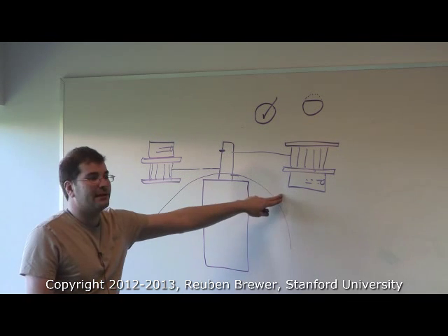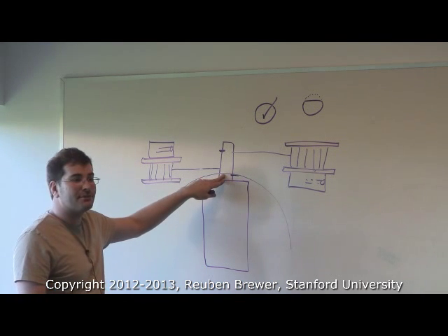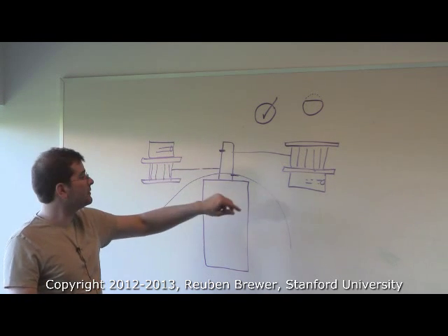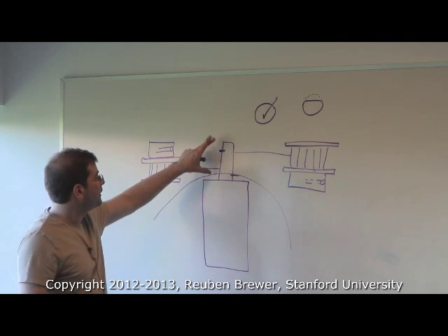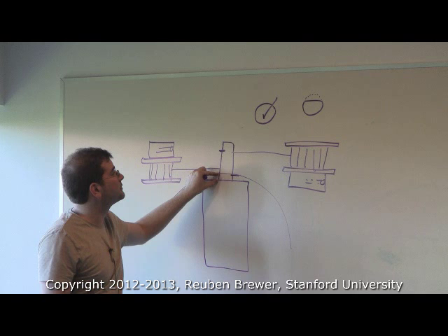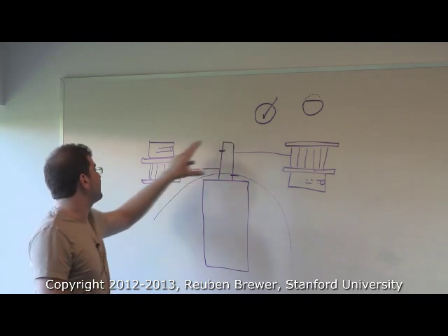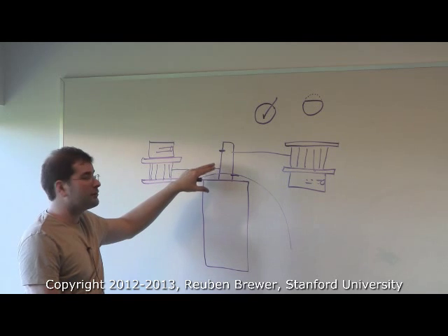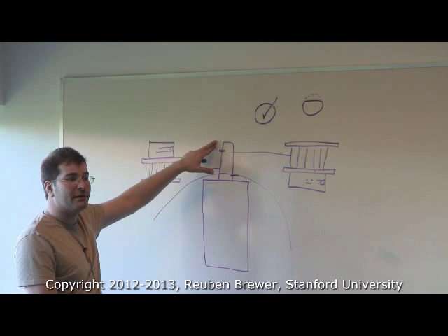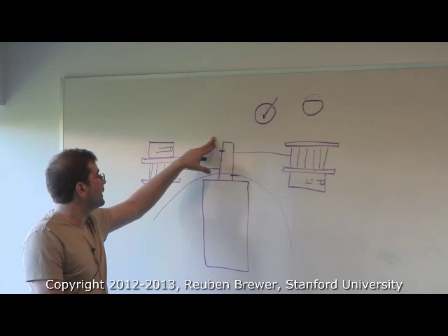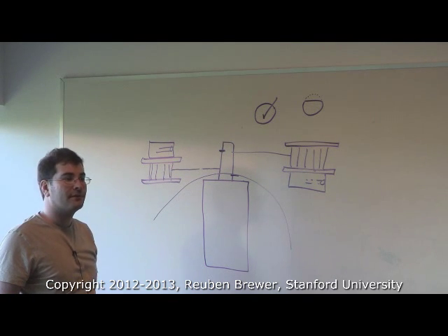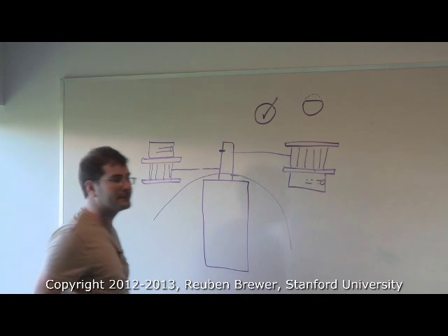Configuration upside down or right side up. If I do it this way, I have to dremel right next to the bearings, which is dangerous, and my force is higher. And if I dremeled the entire thing, most of the shaft is bad for locating. I only have this itty bitty little section of the shaft that's a full circle for locating. If I turn it upside down, my lever arm is smaller, so I have low radial torques. I only have to dremel a little bit and it's far away from the bearing, so I'm good. And most of the shaft is still full circle for locating precisely. So if you have the choice between the two, always do this one.